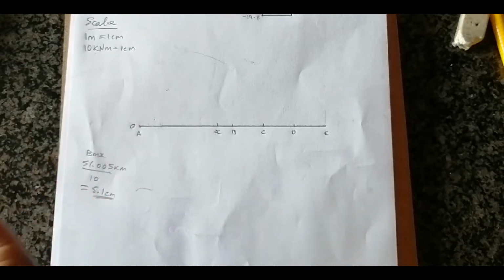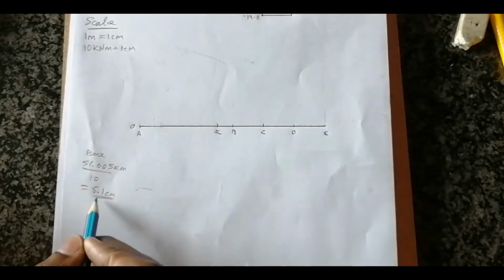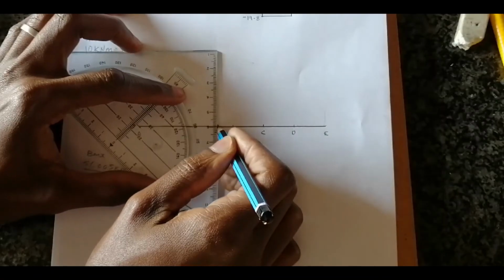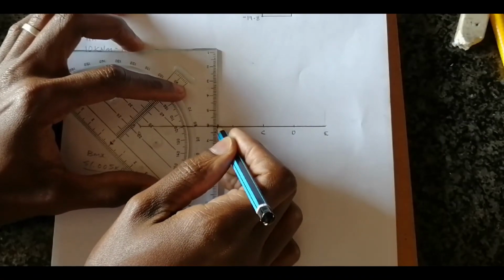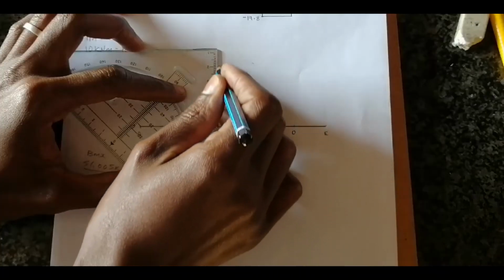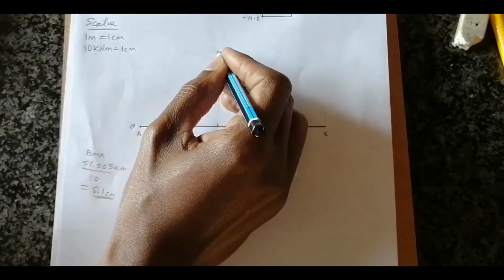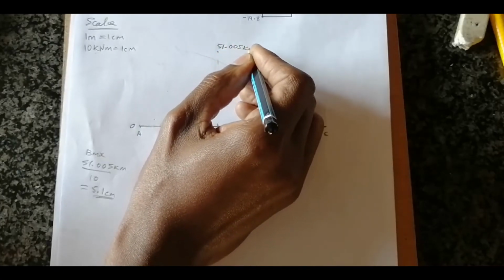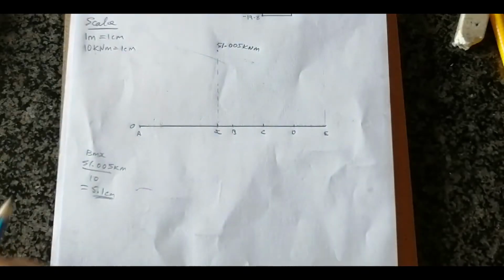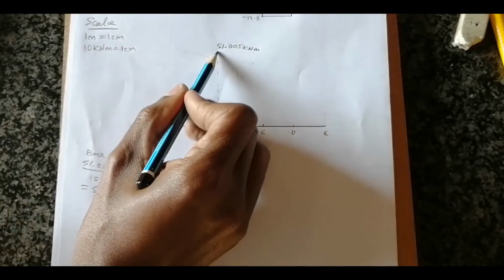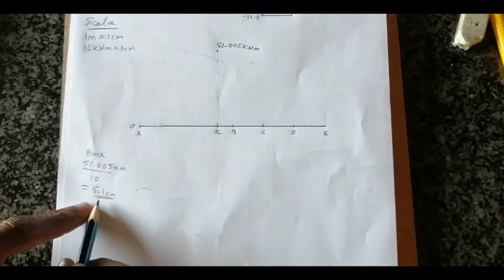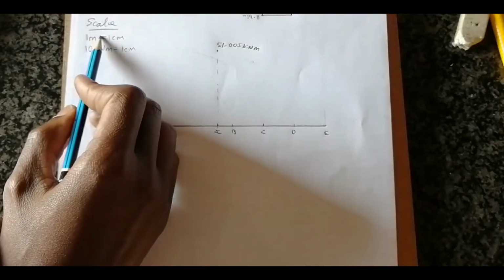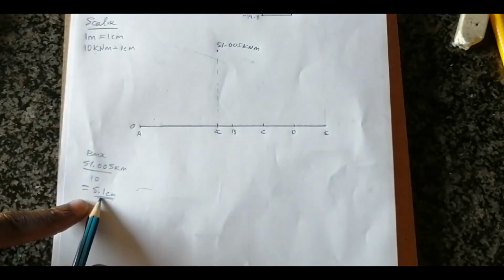So with the bending moment diagram, it is easy. Just go to X and draw this line, but as a dotted line, not the actual line, a faint or dotted line. 5.1. We mark our point and call this 51.005 kilonewton meters. Okay, that is our point. The distance from that point up to our zero line is the distance in centimeters according to the scale that we have used. If you use a different scale, the distances are going to be different.